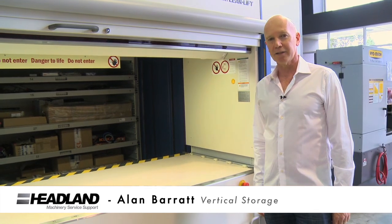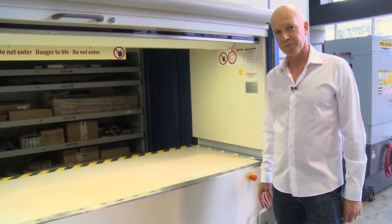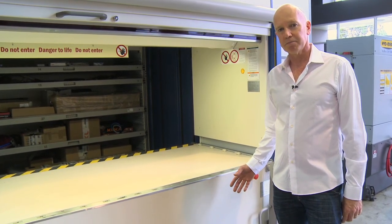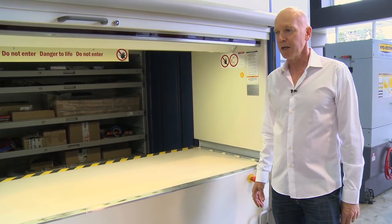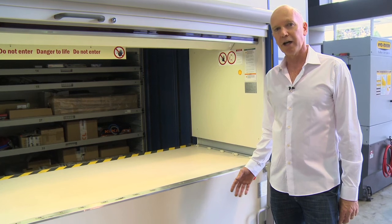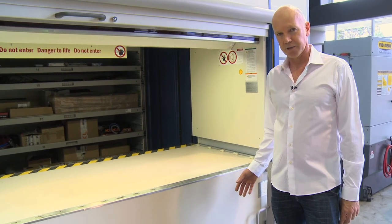The Hanel lean lift has an excellent redundancy system in the electronics. There are nine subsystems in the lift that rely on proximity sensors and electrical components for the lift to operate. To ensure the ongoing availability of the machine, if you experience any fault, you can switch to a redundant set of electronics.